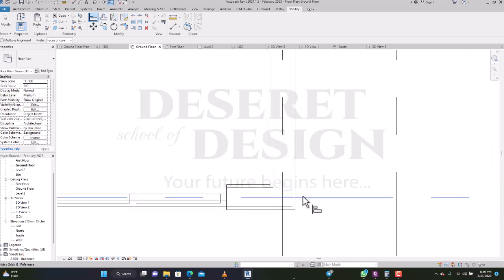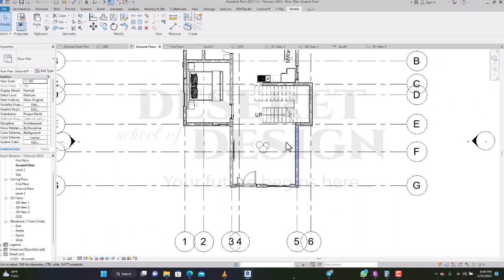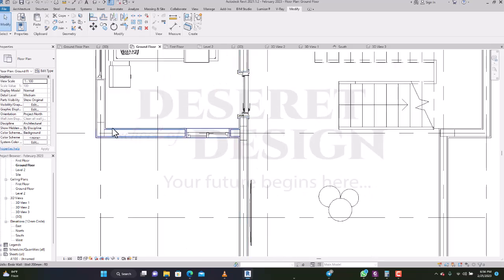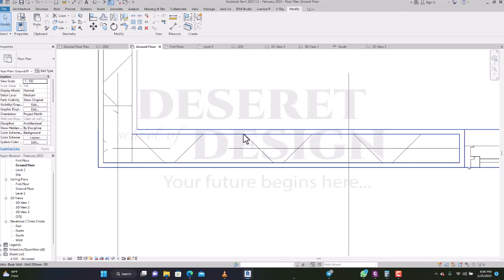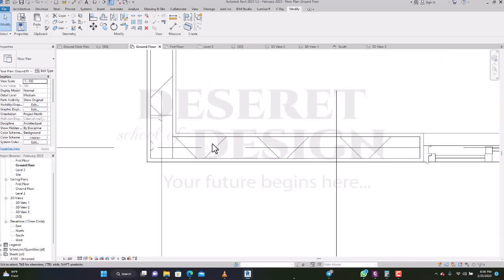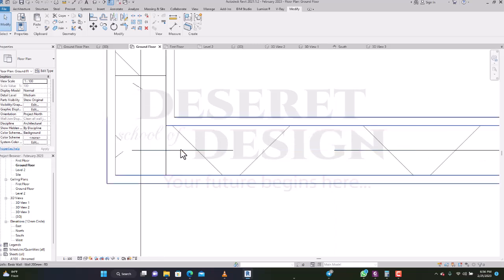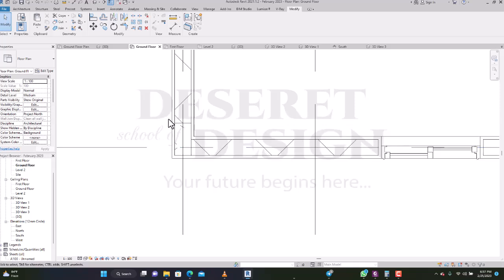Okay. So this is the way to place your structural column. If you don't align it well, and there's a mistake here, and you send the same to another level, that same mistake will run through. Do you get it? So we need to align and correct it well. It's supposed to be flush with the width of our block.